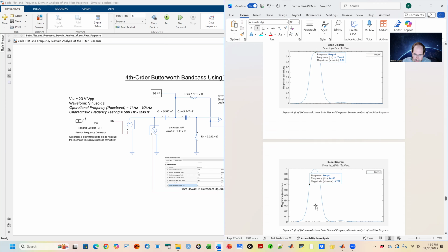Some other information, from doing a bunch of research on this: I noticed that the measured gain doesn't perfectly match the theoretical curve. And this is common in all design. That's expected because real components have tolerances, like 5, 10% resistors. Even capacitors have inherent ranges. In fact, every component does. So that's important to know. And small mismatches cause slight shifts in the gain profile.